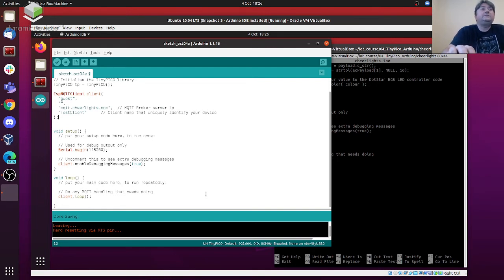What's really nice about this ESP MQTT client is it's that simple. All we needed to do was to tell it the access point we want it to connect to, and where the broker is that it needs to talk to, and what we're going to call ourselves when we say hello to that broker, and all the other stuff is magically happening inside that client loop function, which is a really nice encapsulation of software. It's one of the reasons I'm using this. It's quite neat.